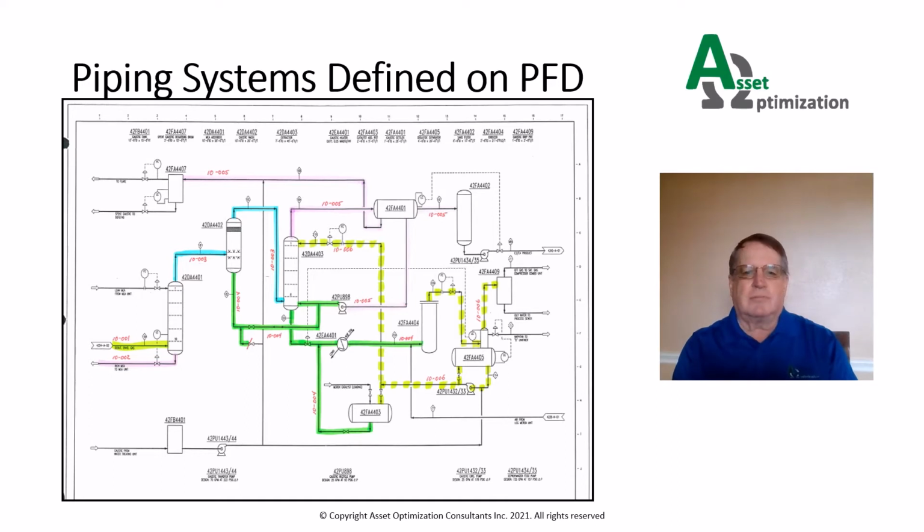Process piping systems are defined and identified on diagrams to organize the piping into manageable segments for inspection purposes. This technique is an alternative to inspecting piping by P&ID line number. Piping systems represent an assembly of interconnected pipelines built to the same design code and containing the same or similar process stream.